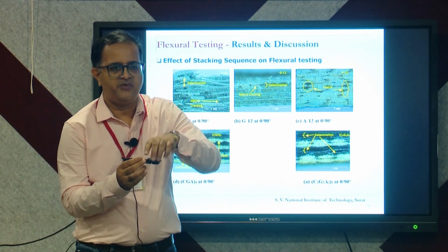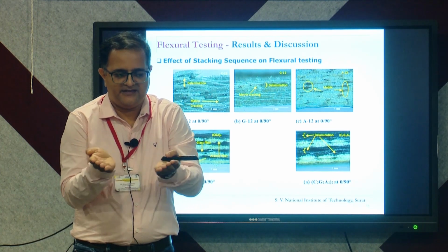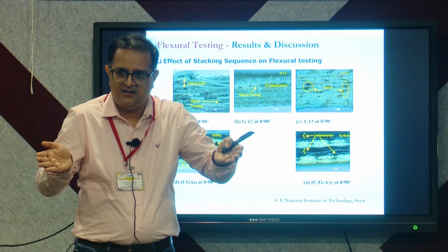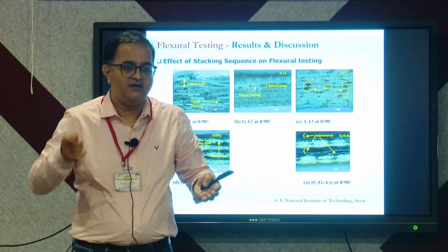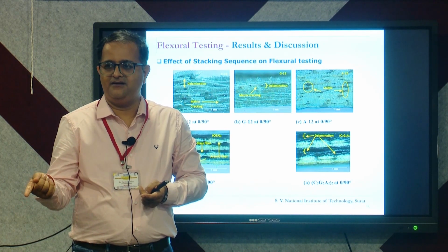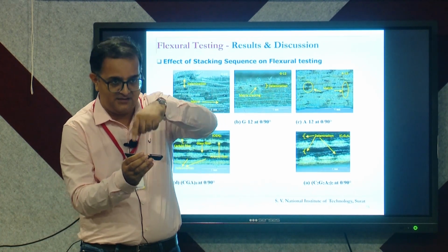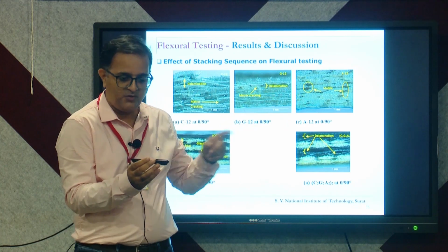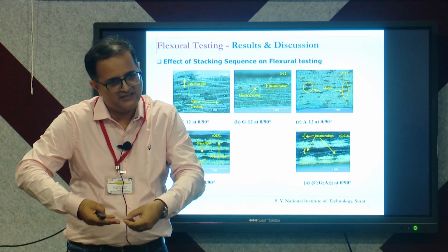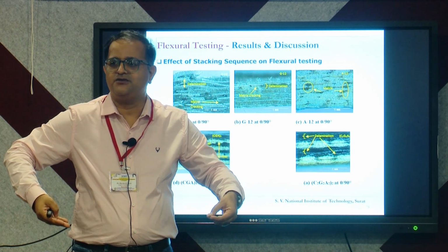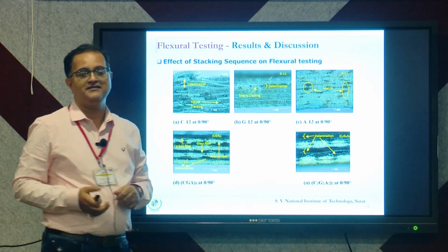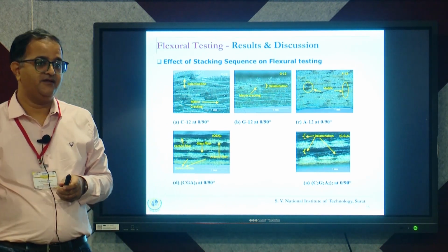In this case, when these parts try to get elongated, there is delamination between them, they get separated, and eventually because of that separation, the resin layer, the matrix, would break rather than the fiber, if they were only unidirectional 90 degree. But here, because you have both, delamination is observed, and the other way there is a bit of extension also happening. So, probably that is how they show better results in 0/90 as compared to the other inclinations.